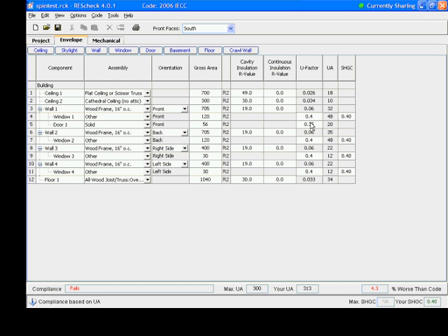So let's take a look at these windows in here. I'll click on one so it's highlighted so you can see that 0.40. And all of them are 0.40. I don't really need to talk about solar heat gain coefficient too much because it's in a climate zone where there is no mandatory requirement for a minimum solar heat gain, but that is still a required input. Now, this U factor of 0.40, well, what's that hard limit?